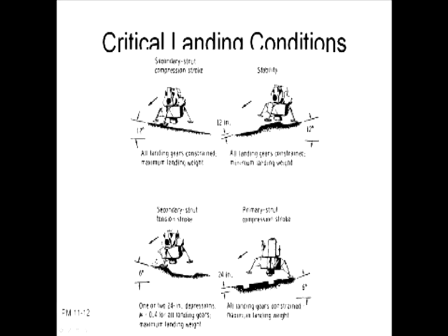Next chart. In our design condition, again, we constrain the foot pads. Anytime you unconstrain the foot pads and let them slide, you're increasing stability and you're relieving energy absorption from the landing gear. So here were our 4 design cases.